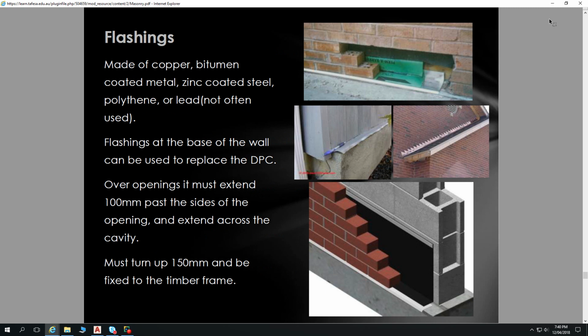Various different flashings here. So this is a flashing at the base of a sheeted wall directing moisture out. It's a flashing that's tied into our brickwork at the change of roof to wall junction. Flashing at the base of the wall to direct moisture from the timber frame out through, and then probably have a weep hole here when all that brickwork is completed.